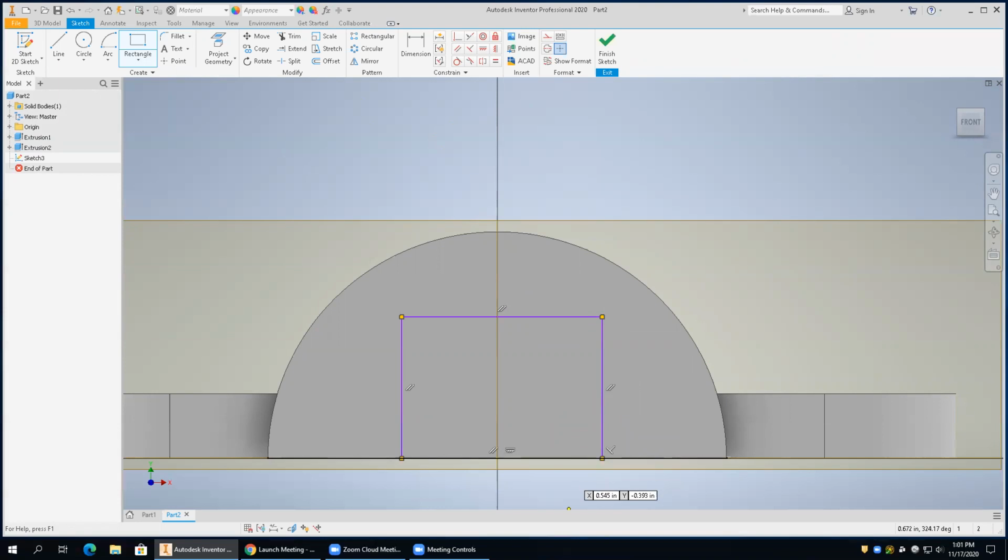So now this thing is going to be a child off of the half cylinder, which is a child off of the base, okay? So you got this parent-child, parent-child, parent-child relationship. So let's throw a few dimensions in this. I'm going to want to have this overall dimension this way. That's going to be, we're going to make that 1 inch.